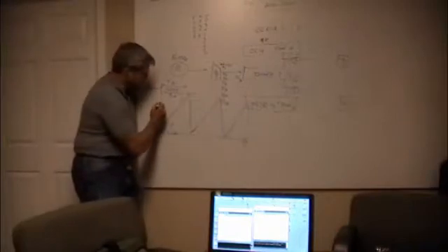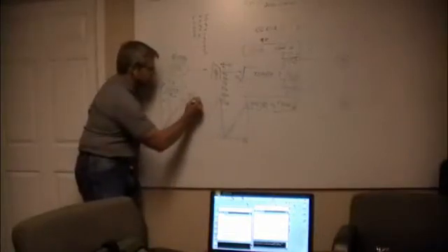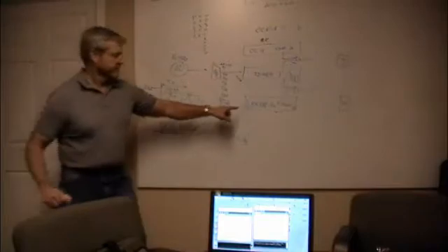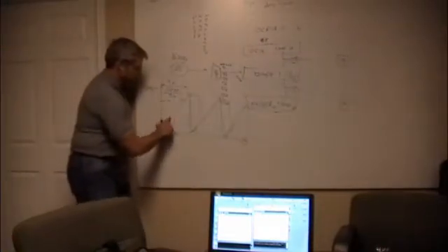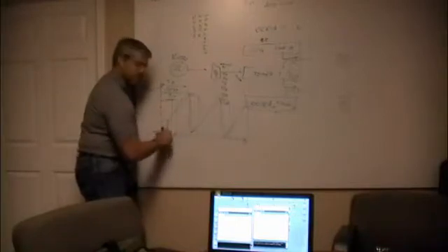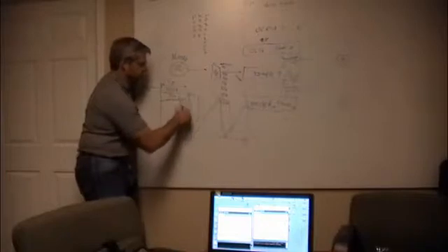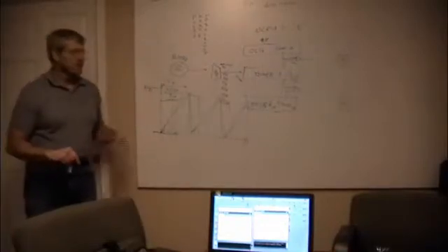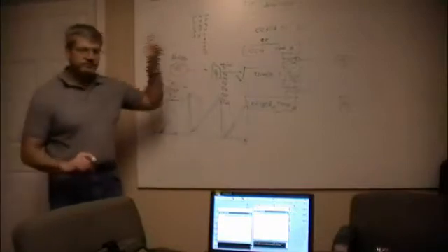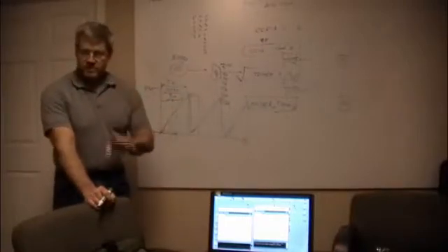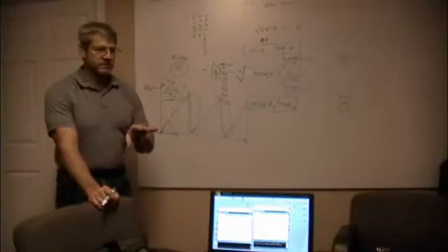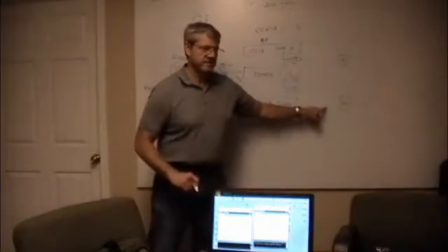So with our example of 2K, what you'll see is this. I've just PWM'd this, right? Because now if I put 4K in here, now this has moved over here somewhere. If it's 8K, then it comes halfway. And if it's 16K, it's right up to the edge and it might turn off for 1 count and then come back on. That's what's going on in the hardware for PWM. Analog write uses this hardware. It's the reason why you can only do an analog write on the pins with those tildes on them, because the tilde tells you it's hooked into one of these.